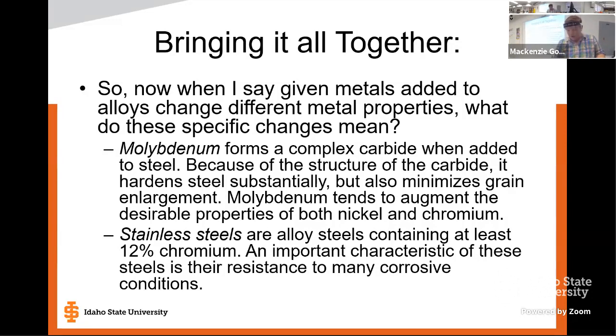Jennifer worked at a solar power plant where they used a moly chromium piping for the fluid that the mirrors were pointed at to put them at high heat. Yeah, Jennifer, that's exactly the kind of application, because when the sun goes down and you don't have that heat coming off the mirrors, you're going to have that metal contract, and then it's going to expand when it heats up. So there's a constant force going on there, right?